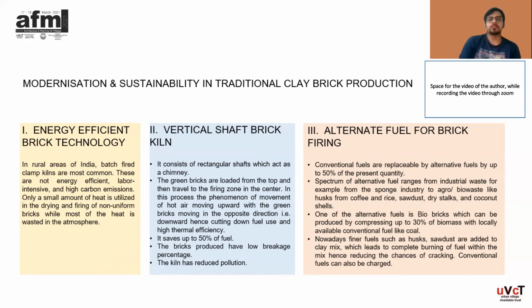In this process, hot air moves upward while the green bricks move in the opposite direction, that is downward, hence cutting down the fuel use and giving high thermal efficiency. It saves up to 50% of the fuel as compared to a normal brick kiln. The bricks produced have a low breakage percentage and the kiln obviously has reduced pollution.